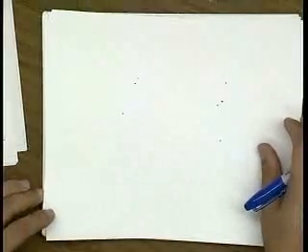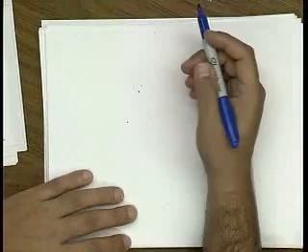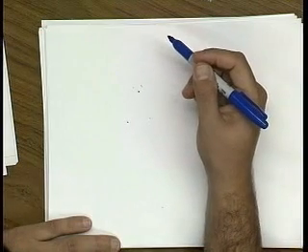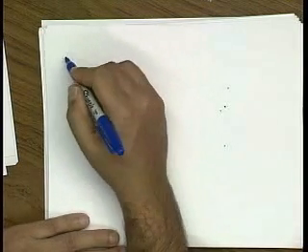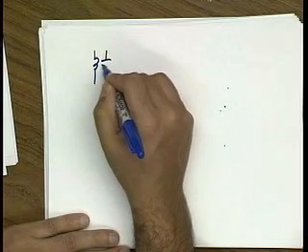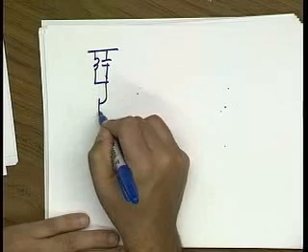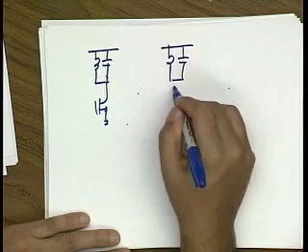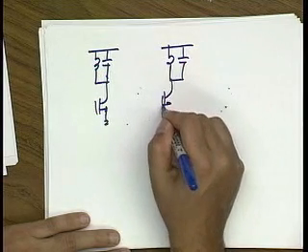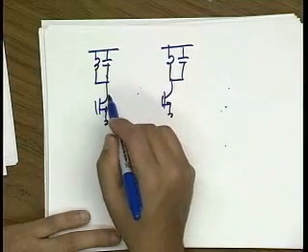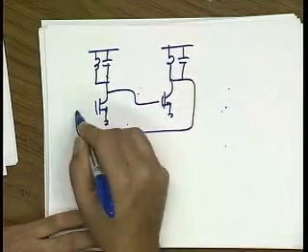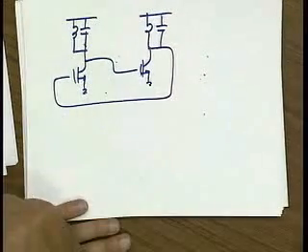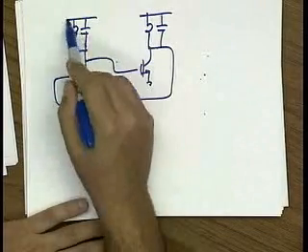Okay, well, another nice trick is to reuse some current, and let me give you an intuitive way of seeing how this comes about. Let's go back to this amplifier and interpret it in another way. Let's say that I have an amplifier like this, and I have another amplifier. So this is an inverting amplifier stage. This is another inverting amplifier stage. And if I just connect them together, I get a feedback system, right? And this is essentially the cross-coupled pair that we just drew, right? So this is another way of looking at things.